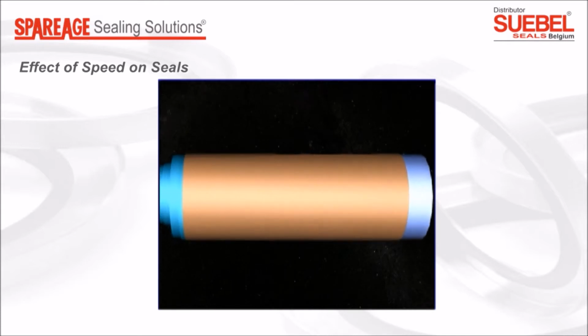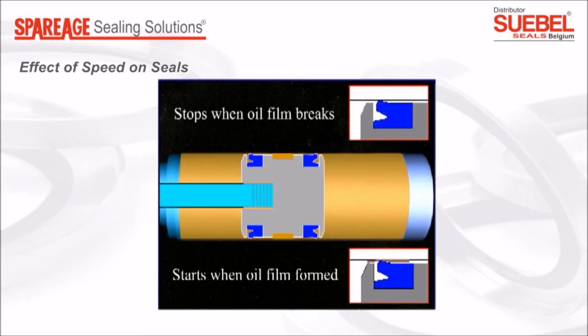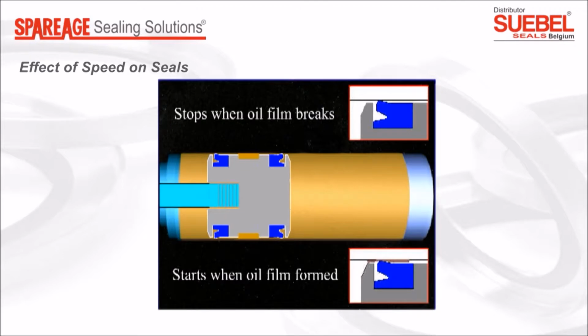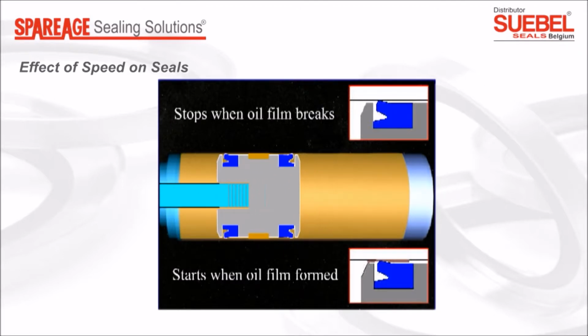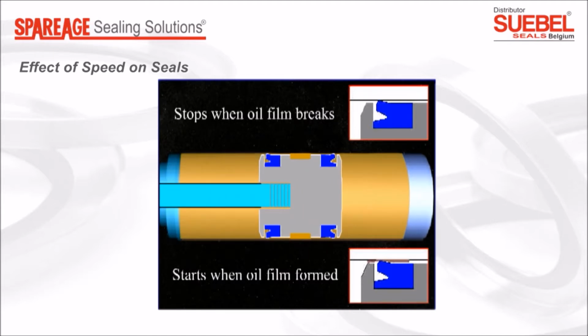At high speeds, the film of oil is often broken, resulting in jerky movement of the equipment. And when the lubrication is restored, the motion continues. Due to this stick-slip problem, and the absence of lubrication film altogether at even higher speeds, or the lack of lubrication properties of the media, have to be considered to select the appropriate design and material of the seal.